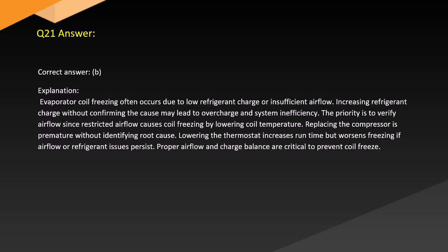Increasing refrigerant charge without confirming the cause may lead to overcharge and system inefficiency. The priority is to verify airflow, since restricted airflow causes coil freezing by lowering coil temperature. Replacing the compressor is premature without identifying the root cause. Lowering the thermostat increases runtime and worsens freezing if airflow or refrigerant issues persist. Proper airflow and charge balance are critical to prevent coil freeze.